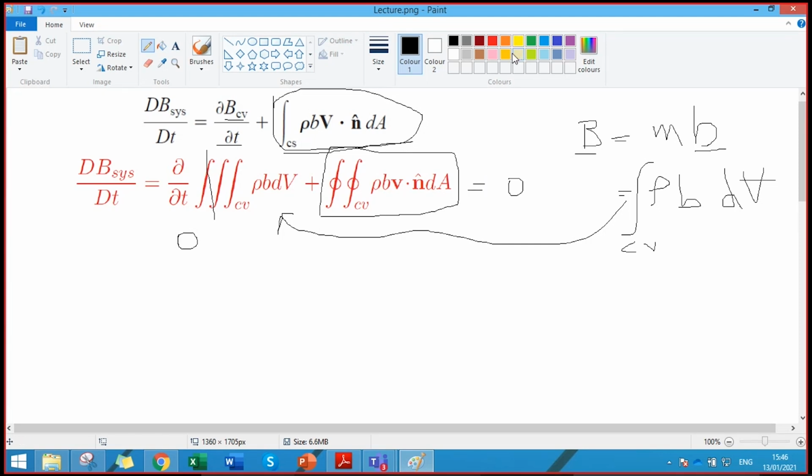Sir, when the perpendicular dot product is 0. And that would be, yes, what would be the physical meaning of that? The fluid is flowing parallel to the surface. Flow is not into the control volume, right? There is no inflow or outflow from the control volume, right? This can be one scenario when there is no inflow and there is no outflow.